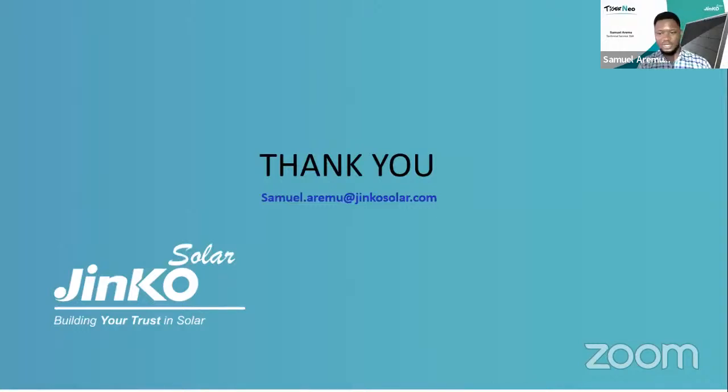For a generator, I'm sure we understand that the consumption depends on the load connected to the generator. So in a PV diesel hybrid configuration, during the day, you are running the diesel generator at minimum capacity, let's say 30% of its capacity. That means your diesel consumption will be reduced because your main energy source will be the PV. Then at night, you switch back to the diesel generator. That means the diesel cost is being halved. If you are consuming, let's say, 24 liters of diesel, it might reduce to 12 liters of diesel. So that has reduced your cost on the generator.